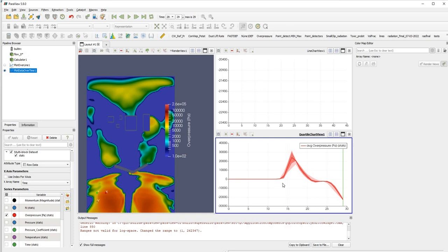And that allows you to calculate the area. If you know the base of the triangle, you know the height, you can calculate the area. And the area, of course, is the impulse that's delivered to the building. That's the energy delivered to the building, so you could quickly approximate that.